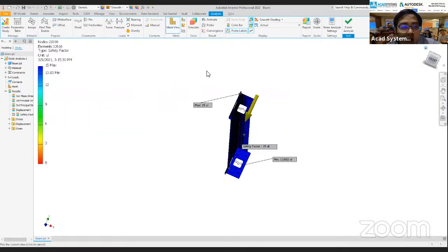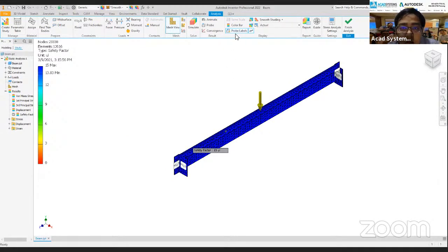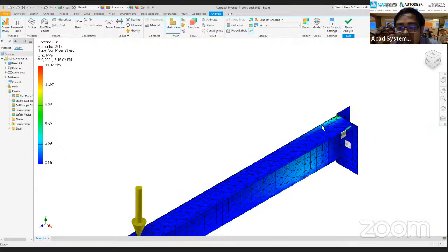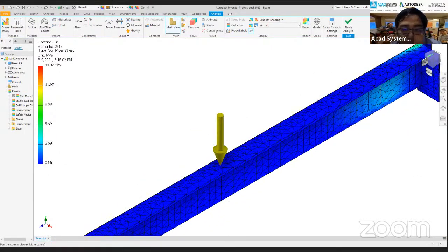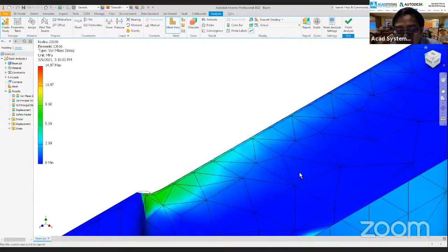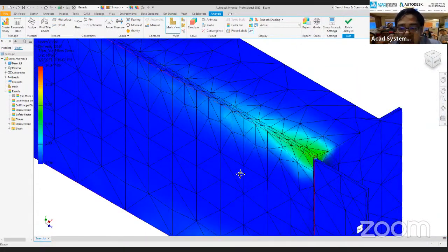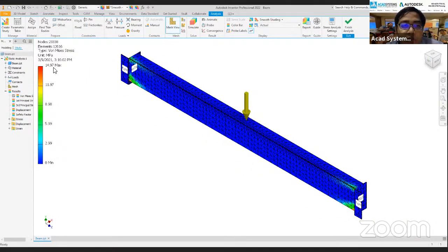So let's say you still want to read the stress value over here. You can see the maximum stress value is around 40.97 megapascals. You can see it is highlighted over here. So the most stress is the highest stress that occurs. By the value itself, it actually holds no meaning. You need to compare the value over here to the material's allowable stress, right? Whether it's yield or tensile.